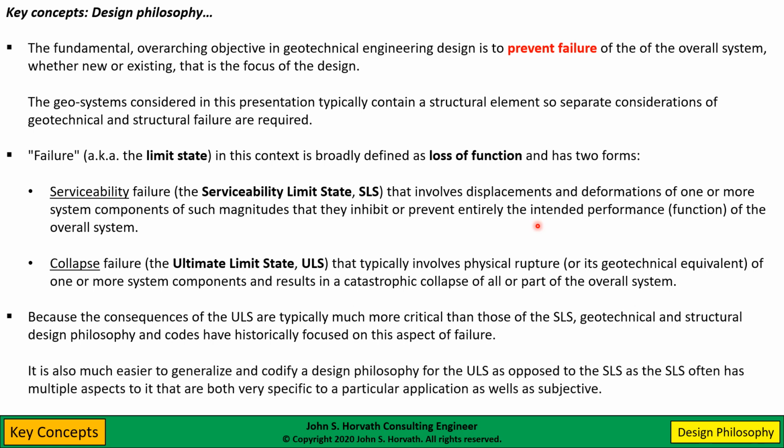It's also, I think, easier to generalize and codify a design for the ultimate limit state as opposed to the serviceability limit state. And this is because the serviceability limit state can have multiple aspects. And these aspects are very specific to a particular application. And more importantly, they're quite subjective.